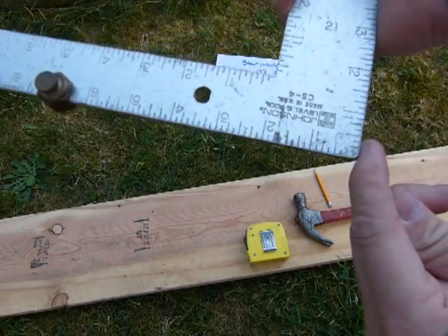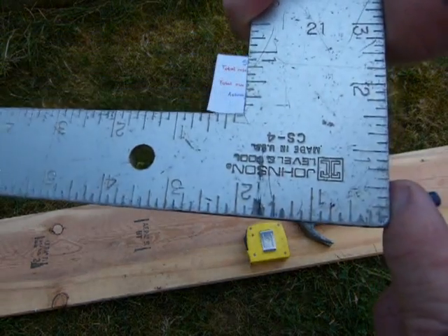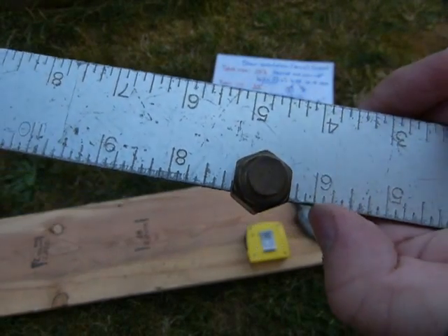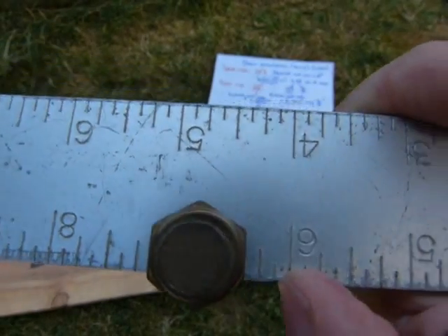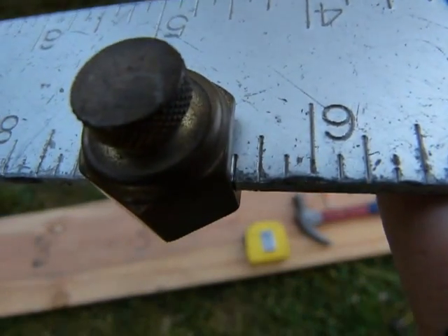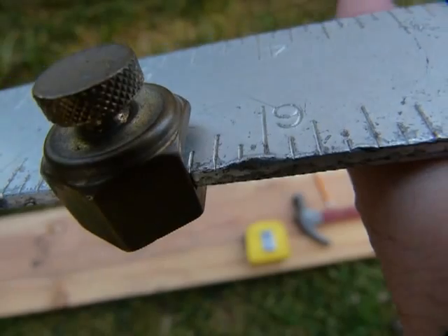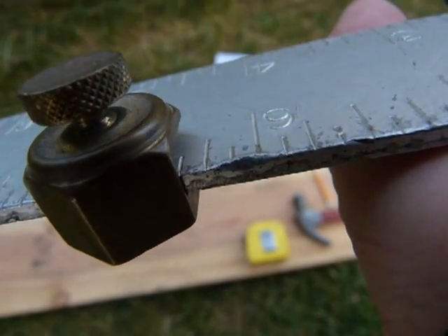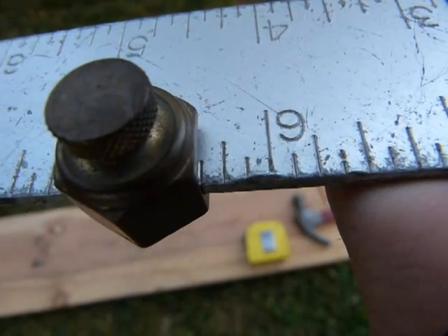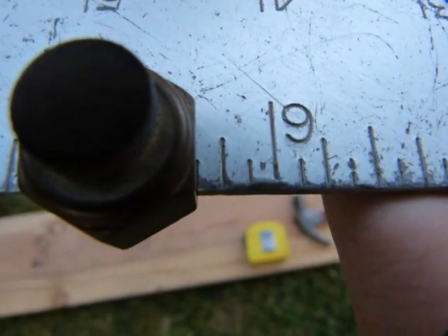From the corner here, this is where 0 is on the framing square, we go 1 2 3 4 5 6 inches and 3/8. There is 6 1/8, 6 2/8, 6 3/8. When the stair gauge is mounted properly, 6 3/8 and the edge or corner of the stair gauge meet in this fashion.